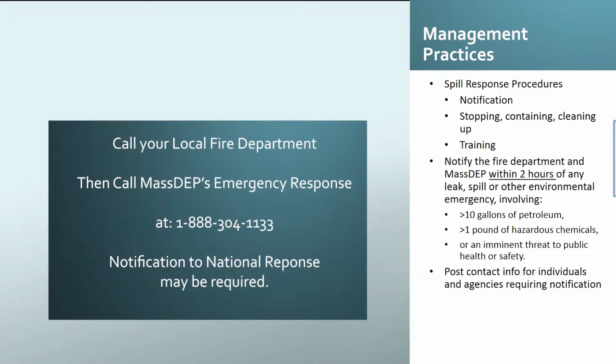So if you have a spill, you need to notify the fire department and the Mass DEP within 2 hours of any leak, spill, or other environmental emergency that involves more than 10 gallons of petroleum product, more than 1 pound of hazardous chemicals, or it poses an imminent threat to public health or safety.